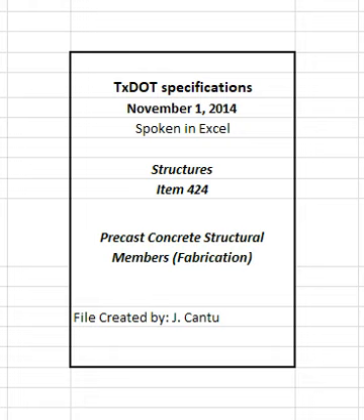4.1.1.1 Prestressed members. Furnish shop drawings for prestressed members unless otherwise shown on the plans or in other items. Submit the proposed designs on forms furnished by the department when optional designs are permitted by the plans. Obtain approval of these designs before casting.